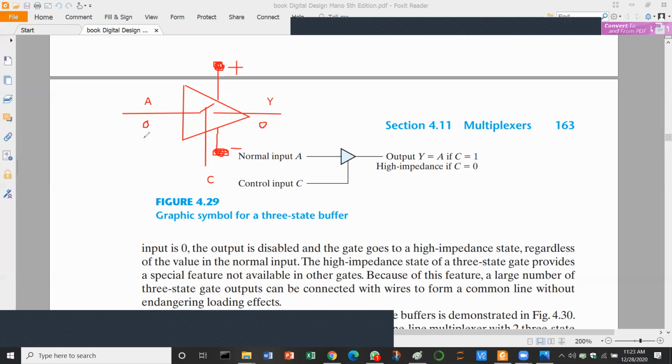And when we want to make it 1, we make the input 1, and then we enable the control, and we send a very short pulse on the control, so that the output changes. So the output will become from 0 to 1, and then the control comes back and turns the switch off, and we have the high level which stays on the output.